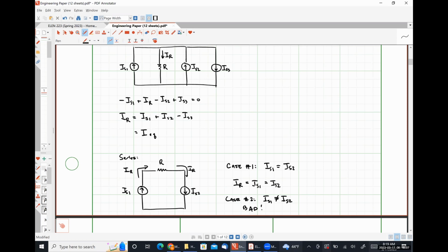And even then, by definition, the two current sources, in that they're connected in series, literally have to be carrying the same amount of current. Like they physically can't not do that. So in my experience as an electrical engineer, there is actually no case where you will ever see this configuration. So just as a heads up.